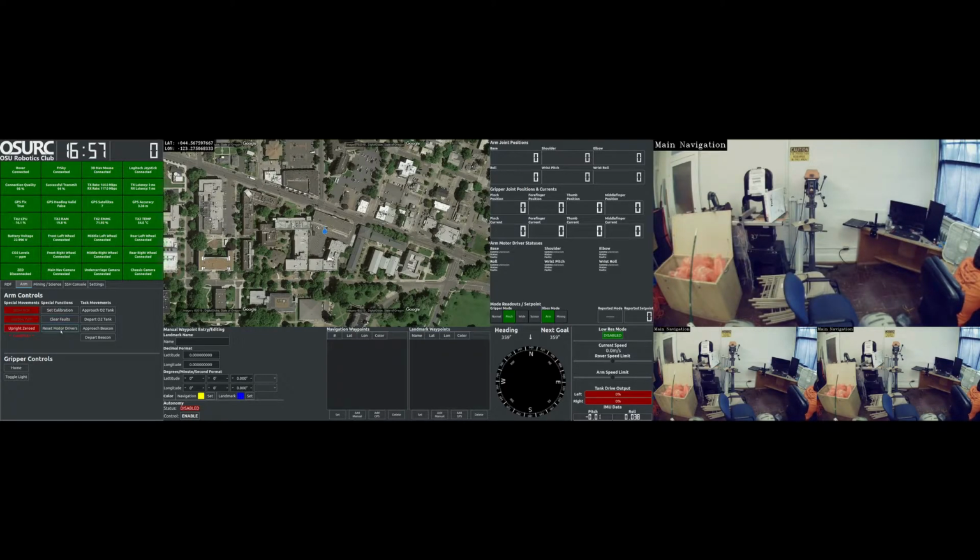You have to be really careful with the movement commands on this page. If the arm isn't calibrated, or if you are not paying attention to where the arm is when you hit the button, it is a sequence of commands for the most part, so it'll move to a known location before continuing the sequence, but if you hit it at the wrong time, it is possible to move the arm into something you really don't want it to hit.